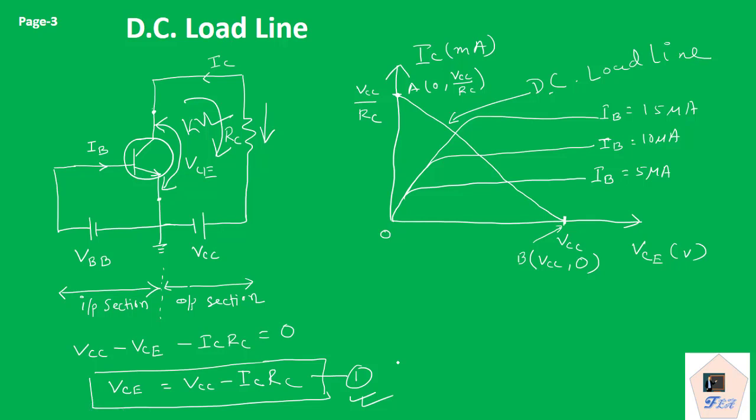Transistor amplifier working in the CE mode. So that is a very important relation. And here if we see, then the DC load line is actually the maximum value of the collector current and the maximum collector voltage applied, VCC applied. So VCE can have the maximum value as VCC. So if we join these 2 points, then we call this particular line the DC load line.